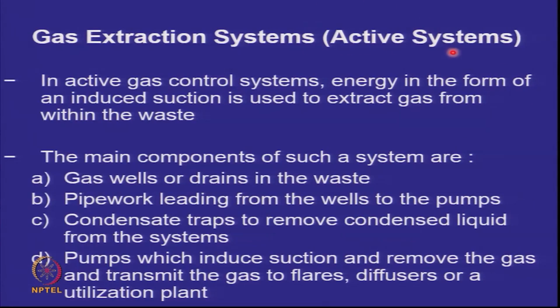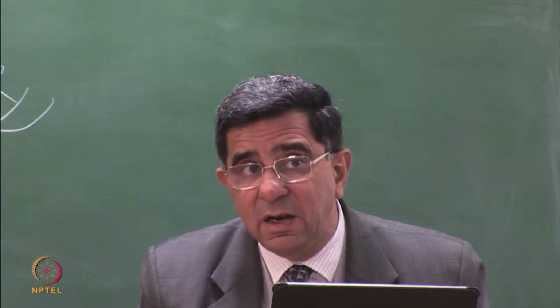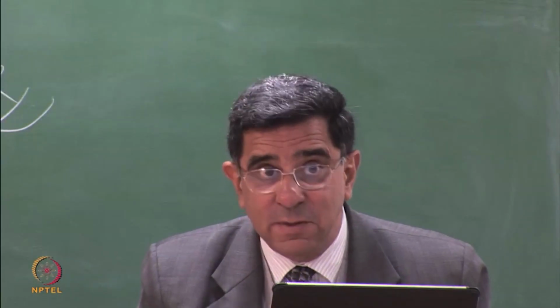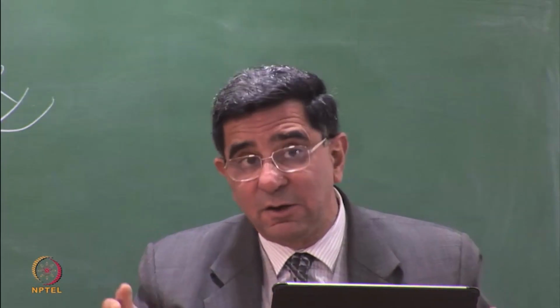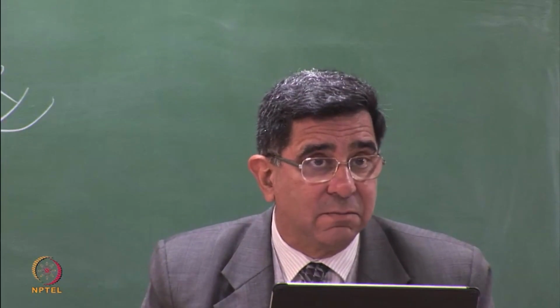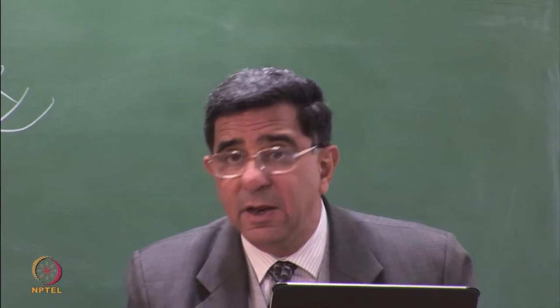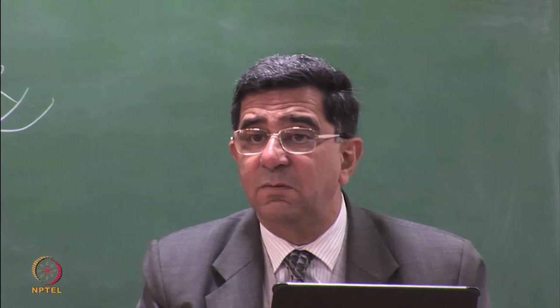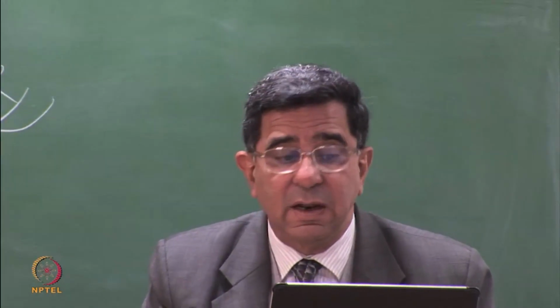So in the active systems, you are inducing suction, nothing else is changed, and that is used to extract the gas. If you keep the system under negative pressure all the time, no methane is going to escape, and therefore landfill fires will not be there. But we have to make that investment, and you have to put a cover at the top. So if you don't close your old waste dumps and you don't do your gas collection properly, you're going to continue with this problem of fires and smoke on the landfill.